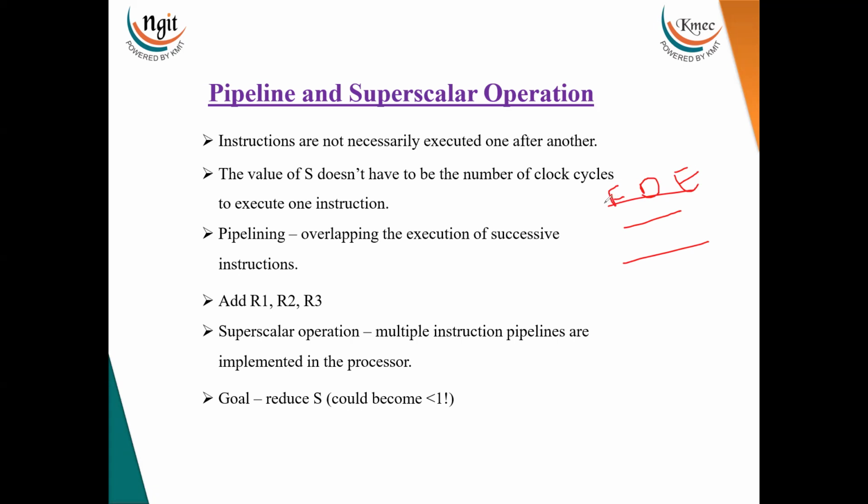The first instruction is fetched from the memory. While it is decoded, the second instruction is being fetched from the memory. And when the first instruction is executing, the second instruction is decoding and the third instruction is being fetched. So with this, if more than 3 instructions are there, from the third instruction onwards, it will take a single clock pulse to execute.